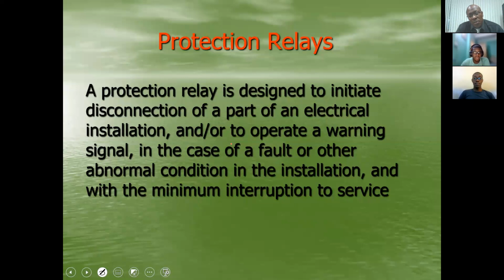So in terms of the warning, as I've said before, sometimes you don't necessarily want to remove the equipment because of the level of disruption that will occur. So for your power transformer, if we think of a relay such as the Buchholz relay, the Buchholz relay will send alarms based on the gases that are created within the oil or the transformer. Now, it does not mean that the winding fault that has occurred is such that it will render the transformer inoperable in a short time.